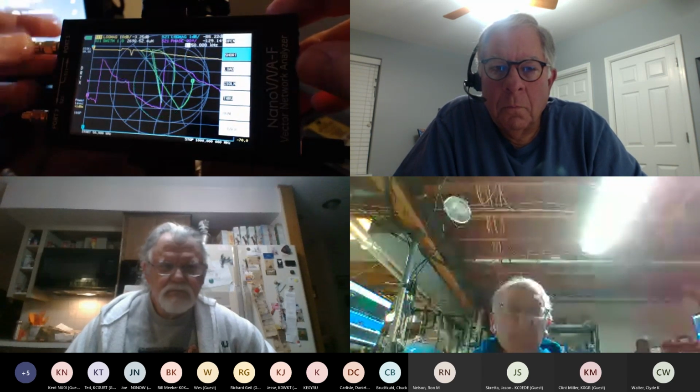You see it highlighted short. So we're going to jump in, and I've got an SMA connector that is shorted. Most of these instruments come with a very simple calibration set that honestly isn't half bad. You can pay the cost of an instrument in a single termination in the professional range. So we're dealing, again, hobbyist scale here, but for what it does, it's pretty amazing. So I've got the short attached, and we'll jump to the load.